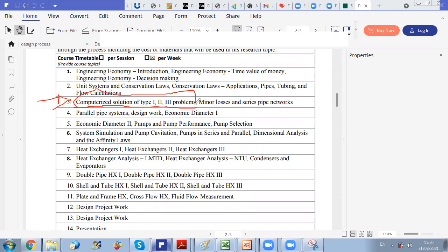For example, in fluids, you work in general, let's say, with one diameter for the piping system. So what will happen if I have a sudden change in diameter? I should deal with two parts. Then instead of having just one friction factor, I might have two, F1 and F2, and the number of unknowns is increasing, which will complicate the solution.